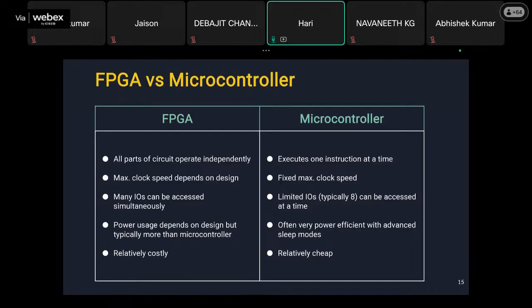In an FPGA, you have nothing like that. You have just your configurable logic blocks with multiplexers and registers. But a microcontroller has a microprocessor, which has dedicated units. If you have a little understanding of how a microprocessor is designed, it has an arithmetic logic unit, memory sections, controllers and data paths. Lots of things are inside a microprocessor. Apart from it, a microcontroller has counters, timers, interrupts and so on.